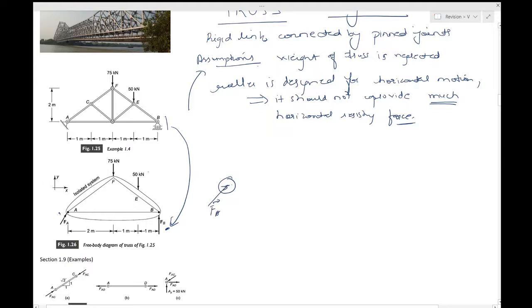Just like in the previous case, we have made an idealization by neglecting the possibility of a frictional moment. We neglected the frictional moment, not the friction itself. I hope that point is clear. It was clear then, it should be clear now. Our rationalization is that even if there is some friction, the smallness of the pin implies that the effect of the frictional moment about the center will be small.